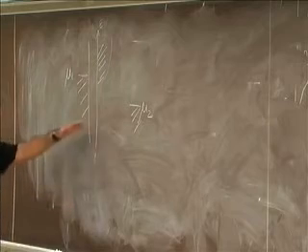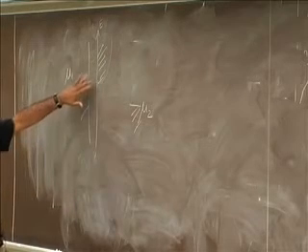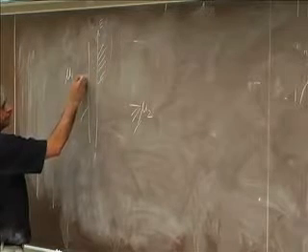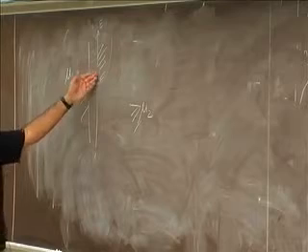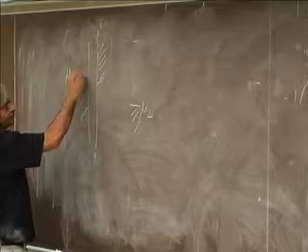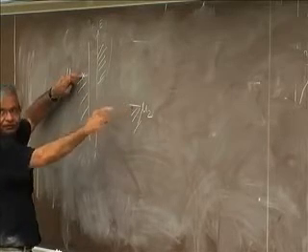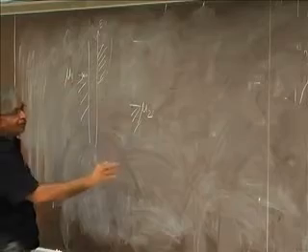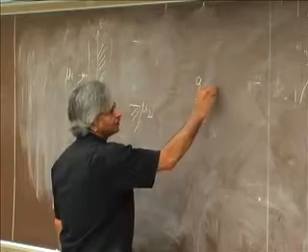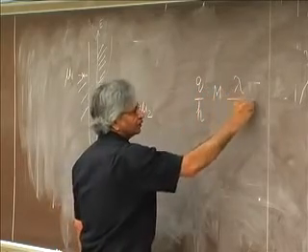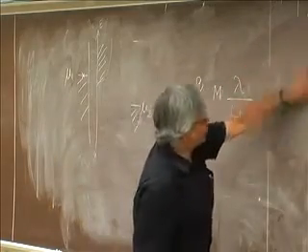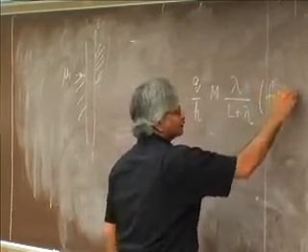Now, one point I made was that supposing you had this fixed like this, and it goes down, when I calculate the current, it doesn't seem to depend very much on the electric field in here, as you think about it, because all that matters is the fact that these two chemical potentials are different, and the way we are calculating it, you would obtain a current that would look like Q over H, number of modes, lambda over L plus lambda. I guess this was the expression that we have been working with, F1 minus F2.